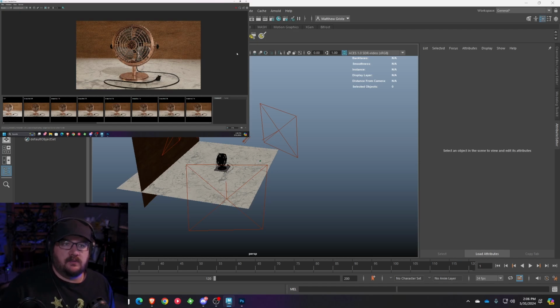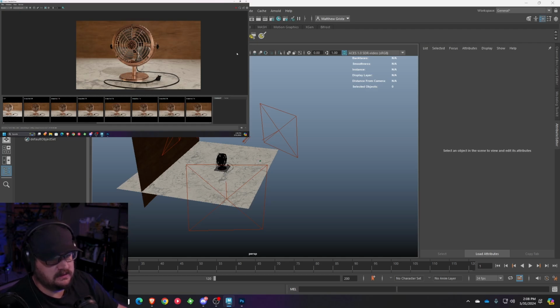It's important as somebody who's new to Maya to really start looking at what some of these settings do and how they work for you and what things they change. Rendering and scene post-processing is a good way to learn how most of these options work and affect your scene, which is why I will go through and tweak things and try to get the best possible image out of it. And then once I get the best possible image, I will turn that optics renderer back on because it's still going to clean up the rest of that grain that I don't want to see. So we can see that whole render took about 2 minutes, so pretty rough.